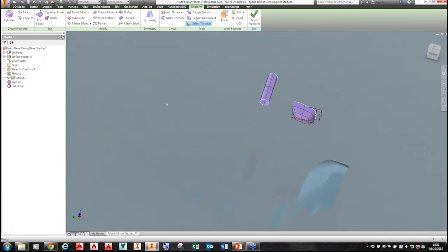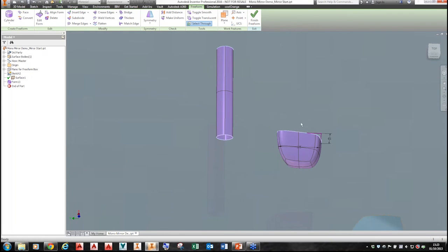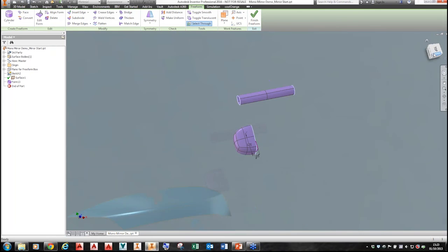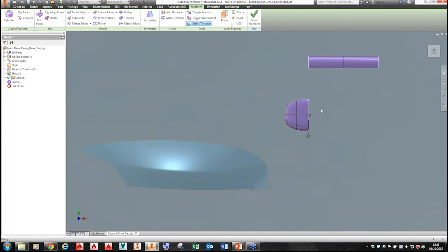So I've got two components. Imagine that at the moment this wing mirror is pointing basically straight down the car, because imagine the car's going along in this direction. I perhaps want to turn it so it points a little bit towards the driver. So if I go to the plan view, so I'm going to go to top, I can see that I want to rotate it counterclockwise just a little bit.